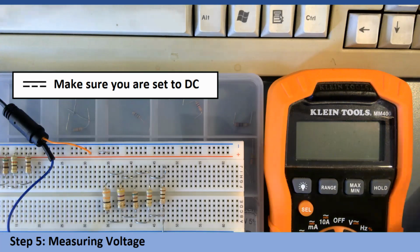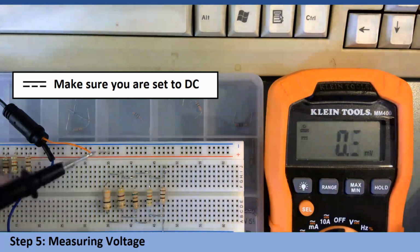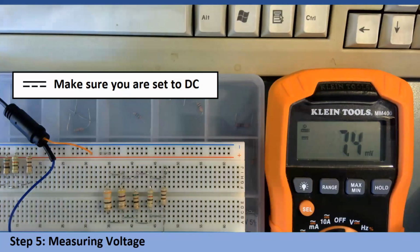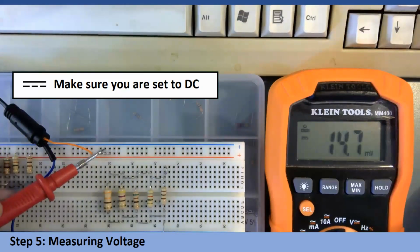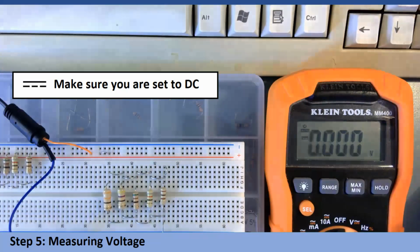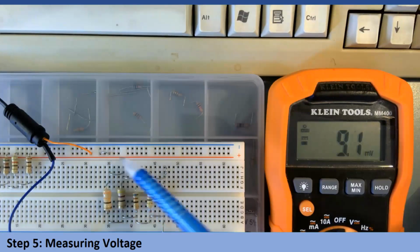So I'm going to turn on my meter to volts, make sure it's on DC, and I'm going to check my voltage across the entire circuit, watching polarity, of course. And my power supply is putting out 4.56 volts. That's the voltage that we require. Notice that I've opened up the circuit. The workspace is not connected to the power rail.